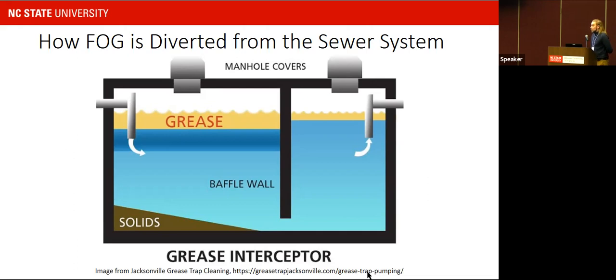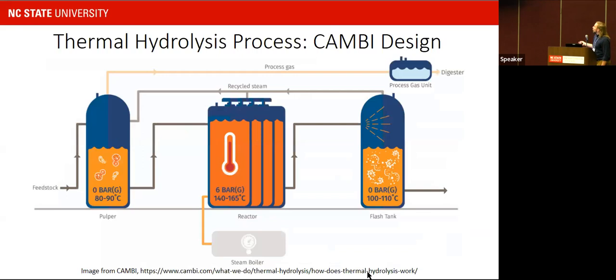There are alternatives. Some people try to compost it and some people try to use it as a soil amendment, but those processes are difficult because of the high energy content and the tendency of the grease interceptor waste to coat things in a lipid layer that prevents oxygen introduction. And for the energy recovery part, full-scale systems have a recycle that allows recovery of heat, and they are much more efficient than our lab scale one. It's just because of scale.